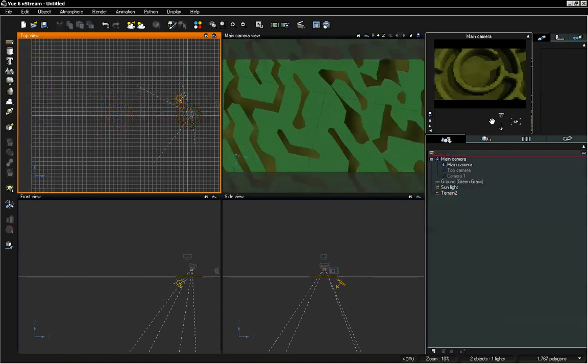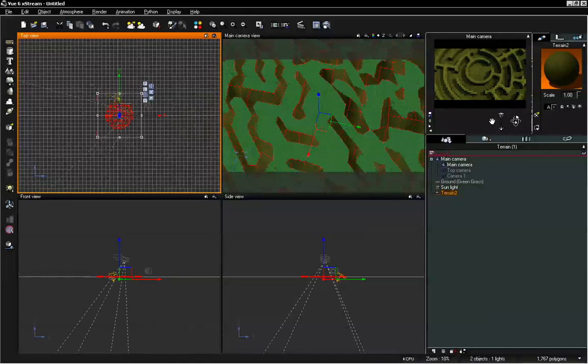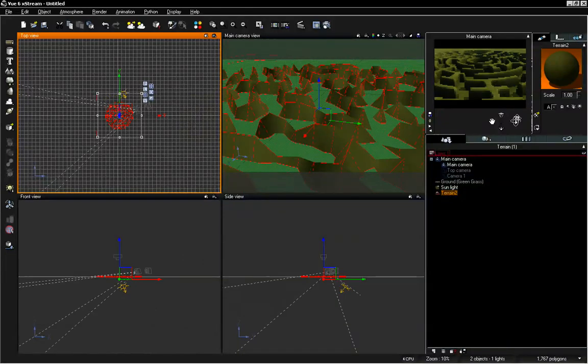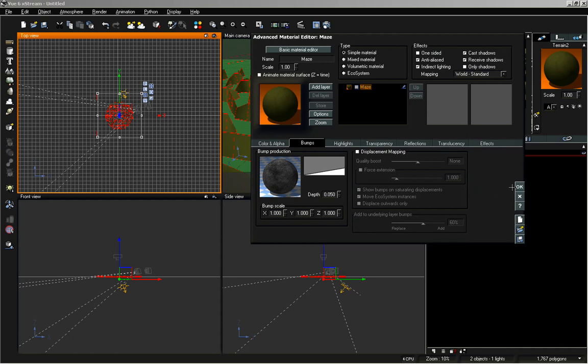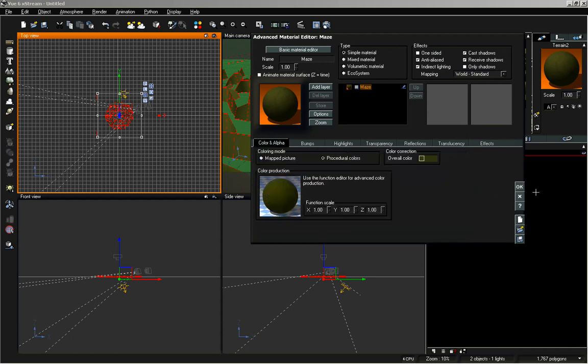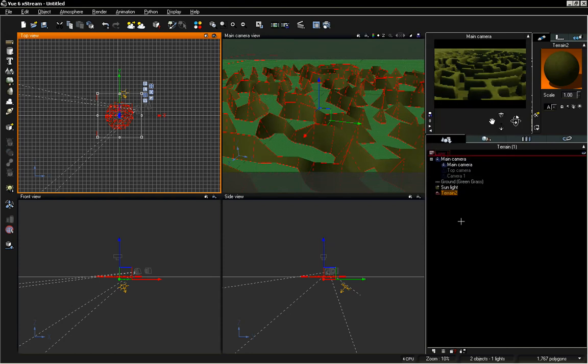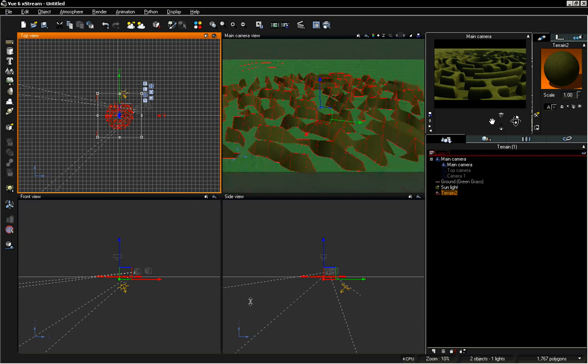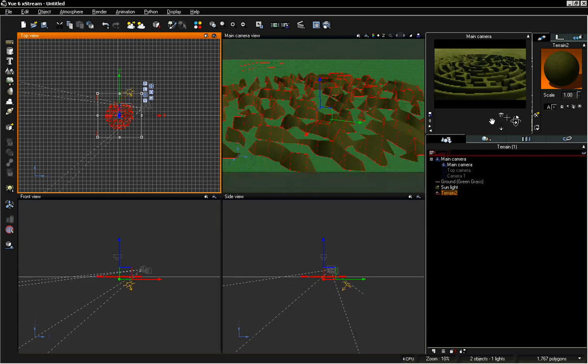And mainly what we could do is go into the plant editor and really try to make a hedge object that will work correctly and look correct. But sometimes that's just not going to turn out the way you want it to. So this is really my preferred method. It's just using the terrain, and then you just want to customize that procedural to add the little bit of extra variation to it, and then really play around with that bump map to get it to look correct.